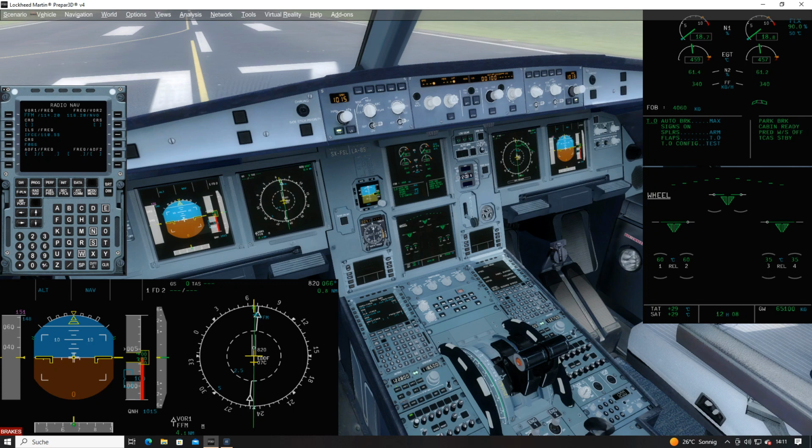From the data on our charts, we can choose the altitude we're climbing to, which today I pick 5,000 feet. It might be 4,000 or 5,000, I don't know the exact value, but I take 5,000. So we have the altitude inserted. We do have a lateral flight plan, how to proceed. We do have a radio aid, just in case for situational awareness. So all data is now fed into the system, and we're ready to go.